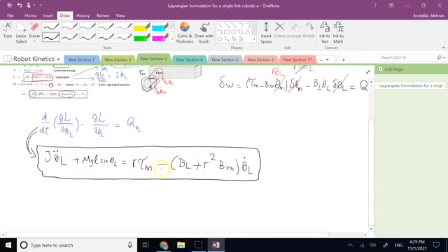And this is going to be your governing equation of motion for a single link robot if the torque from the motor is tau m, and here we neglect the electrical circuit and the voltage to that electric circuit that generates tau m. So input, we consider it tau m, not the input voltage to the motor. And if you remember, this J effective here was J of L plus r squared times J of m.